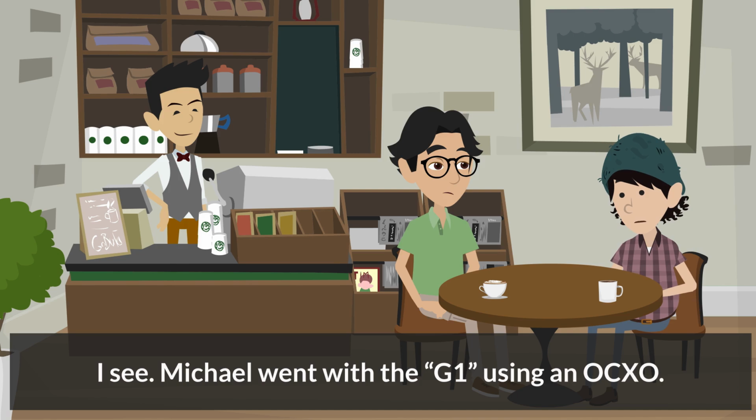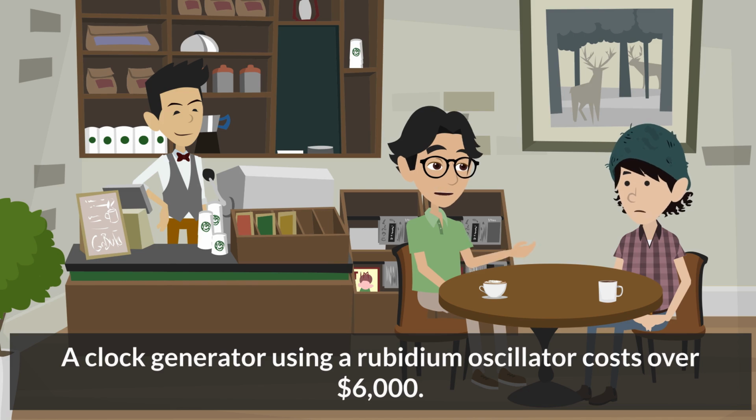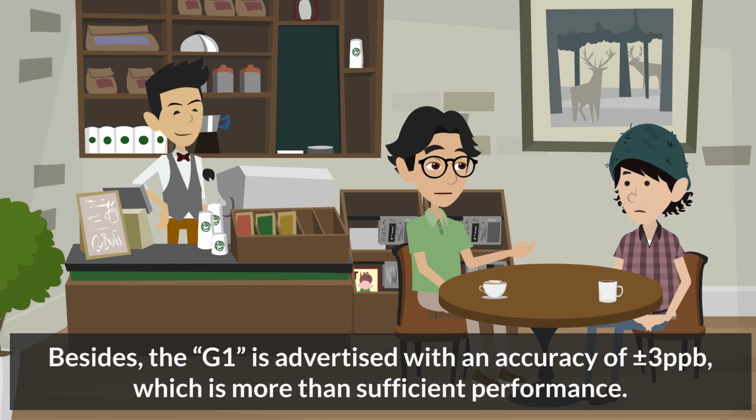I see. Michael went with the G1 using an OCXO. A clock generator using a rubidium oscillator costs over $6,000. Besides, the G1 is advertised with an accuracy of plus or minus 3 ppb, which is more than sufficient performance.